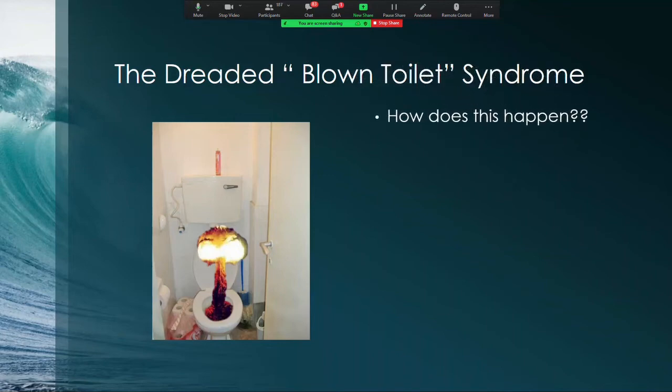What makes this happen? What is the major contributing factor to this issue? And you notice how I said that, major contributing factor. There is no one cause, but there's one cause that is predominantly the issue, and it deals with airflow. So if you think about the airflow that's in the nozzle, if you're a truck operator and you're running and your helper's with you and you put the nozzle in the line and send it up the line, and you send your buddy up there and he hasn't released or removed the cover and he has to try and pull it off with the nozzle in there, you have a feel for how much vacuum, how much air is being brought in there and going on.